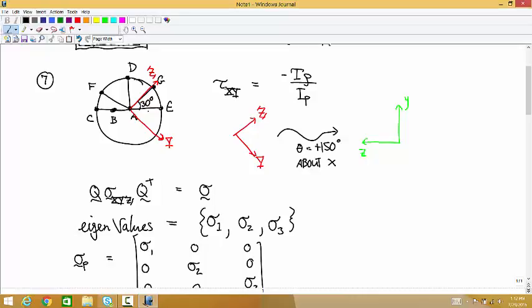So for C, if we had to rotate C's coordinate system, we wouldn't rotate it at all. For C and B, you don't have to rotate at all because the capital coordinate system is already the given one. What did you just say about torsion? At the origin there is 0? Yeah, right at the center of a circular cross section, there's never any stress due to torsion because your rho is always 0. Oh, okay, yeah, makes sense.